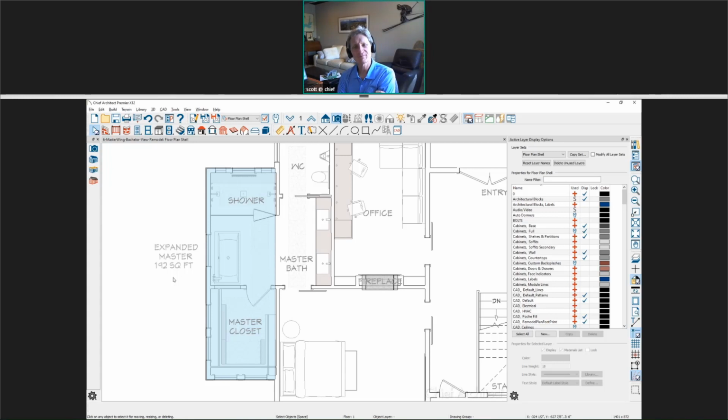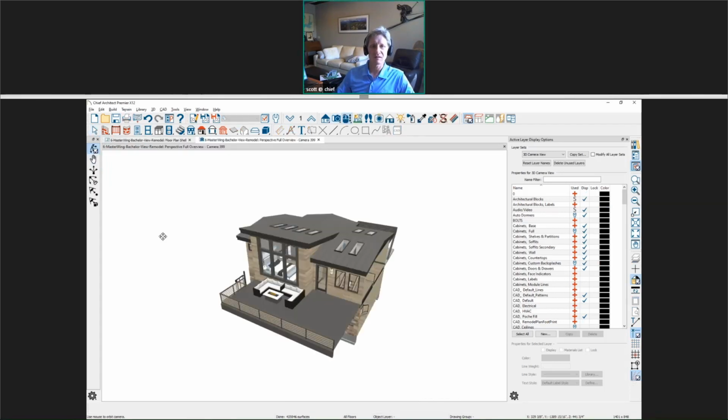Okay. So if the building is fairly straightforward, you can do that on the back of a piece of paper, no problem. But many buildings, especially the historic buildings, are very complicated in shape. And I've had to go back to using SketchUp to remodel the building, just using plain lines, nothing fancy. And then use SketchUp's built-in tools to calculate the volume of the building. And I don't think it's a great step for your programmers to devise some kind of formula to do that.